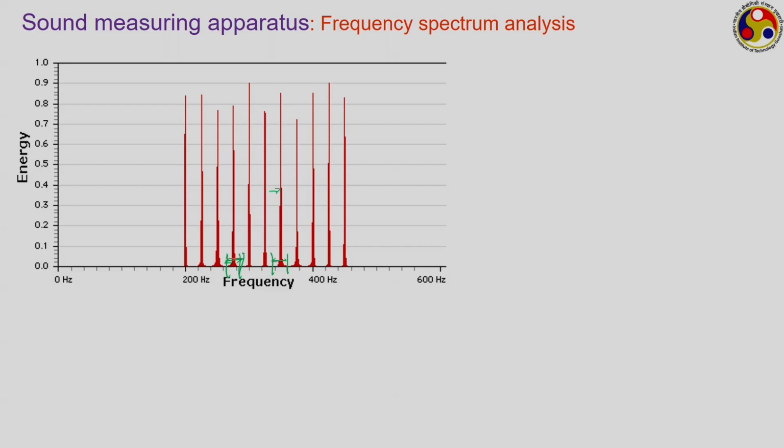Finally, these are the common sound measuring apparatus, and there are a few others also, but the working principle remains more or less the same. That is always the sound wave, which is a pressure wave, hits certain kind of diaphragm, and the oscillation is transferred to the diaphragm, and as the diaphragm starts to oscillate, that oscillation is sensed using suitable circuitry. Now, the sensing method keeps on changing, or I should say the internal mechanism, internal circuitry keeps on changing. However, on the sensing side we always have certain kind of diaphragm configuration.